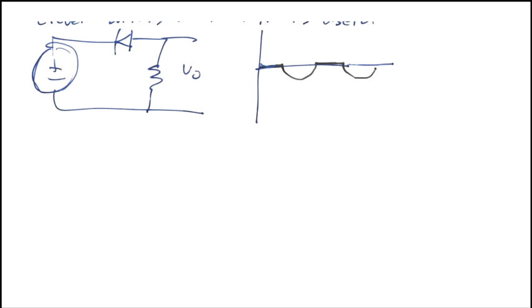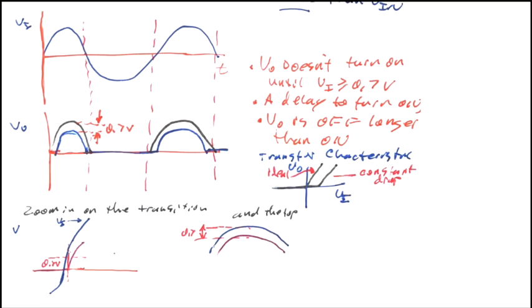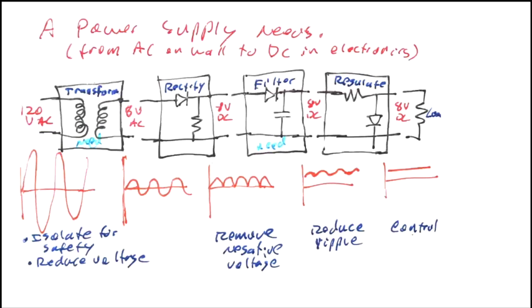So when the output is going high, the other peak is 0 if we have another diode. We could use two diodes, one facing one way and the other facing the opposite way, and that's leading us to how we can get that kind of full rectification of both halves of it. If we can build two separate circuits, one that gets the positive half, one gets the negative half, and then add them together with one of them being inverted, then we'll have it. And it's fairly straightforward to do that.